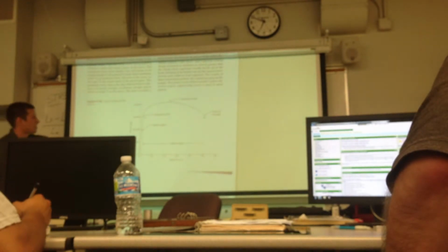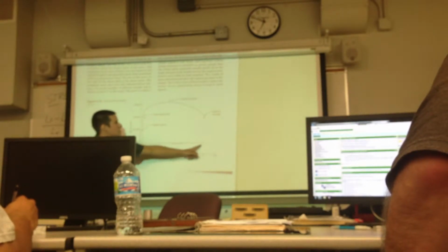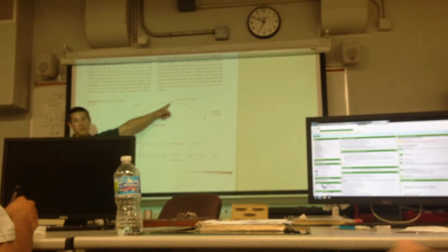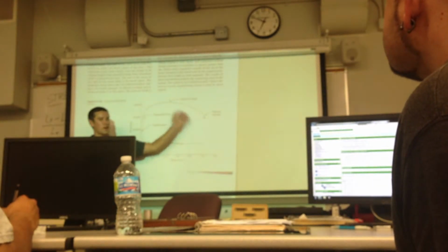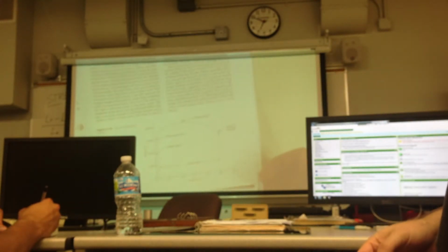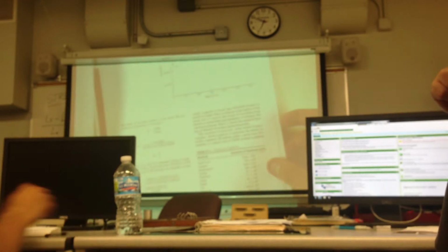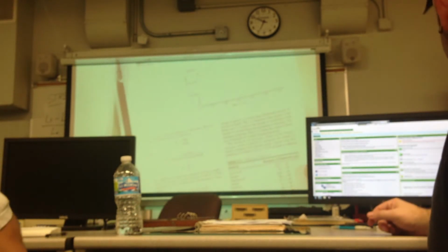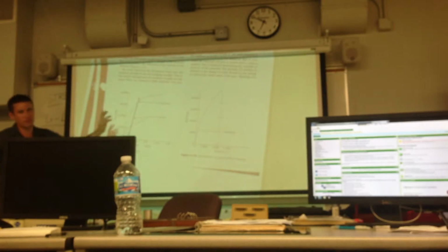So here's what we're talking about here. The elastic region, right? The plastic region. We have the tensile strength or the ultimate strength. Your rupture strength. All this is catastrophic runaway, right? That's probably a stress strain curve for a very hard steel. They talk about the modulus of elasticity, which is basically the slope of this. You don't have to really worry about that.